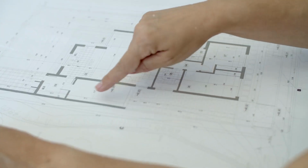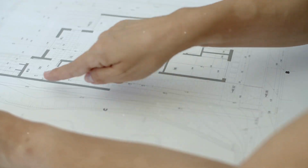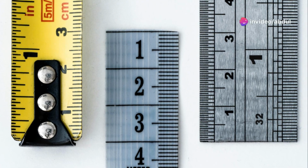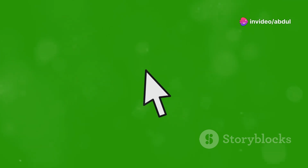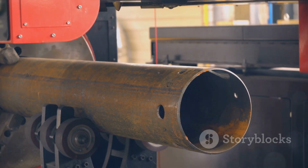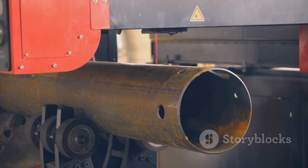To add dimensions, select the Dimension tool from the Annotate tab. Choose the type of dimension you need, such as linear, aligned, or angular. Then click on the points you want to dimension. For example, to dimension the length of a pipe, click on its starting and ending points.